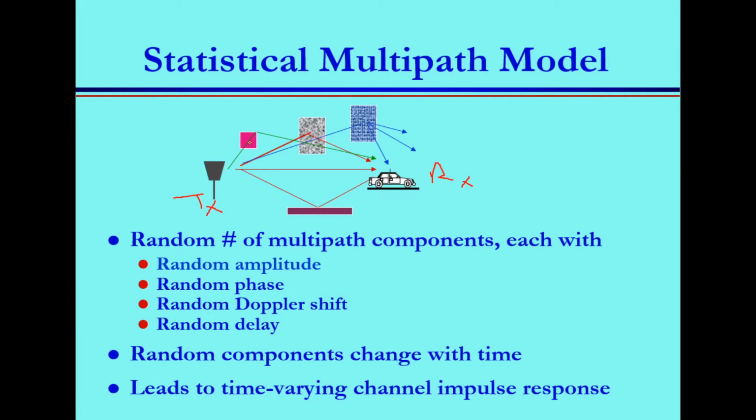Of course. If the transmitter or receiver or the environment is mobile, you will get this Doppler shift. So if you put a fan and you let it run, it will affect your signal. Imagine the transmitter and receiver, both of them are fixed, but due to the environment, you get this Doppler shift.